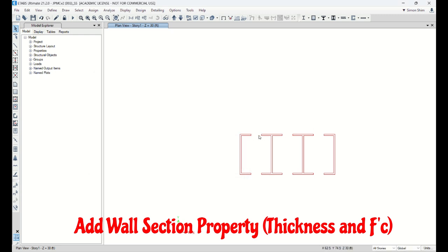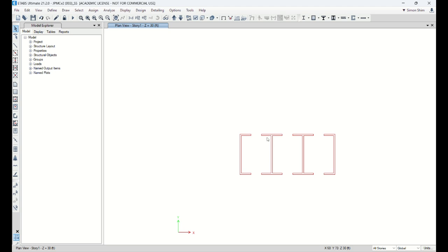Also, we need some beams because this wall has to be tied so that they do not work like a sideways, unbraced system, because the wall is also like a C shape and I shape, channel C shape and I shape. It needs to be braced, which actually increases their lateral stiffness.